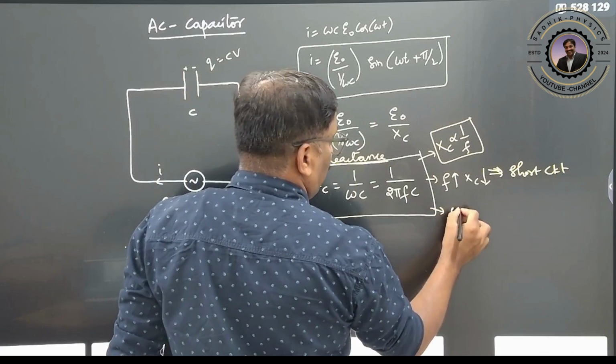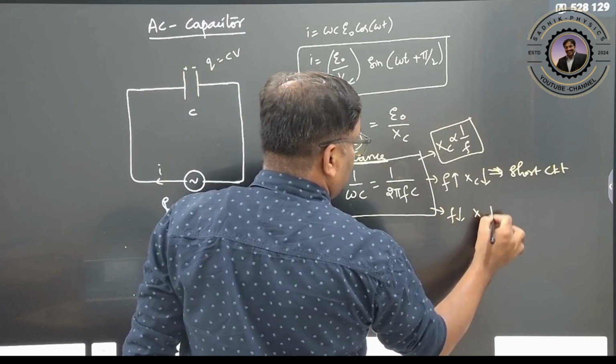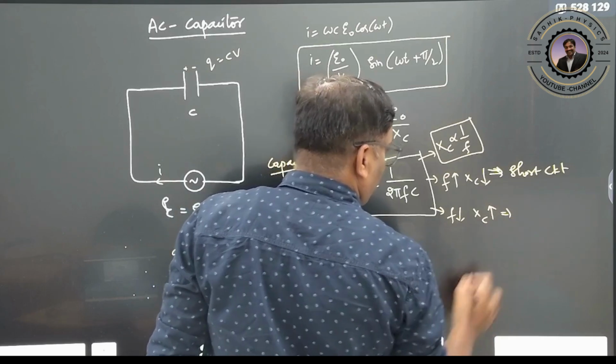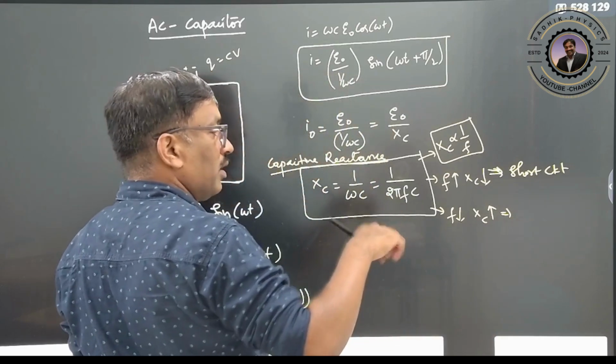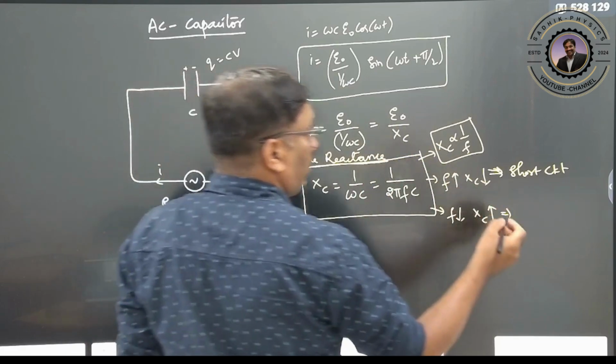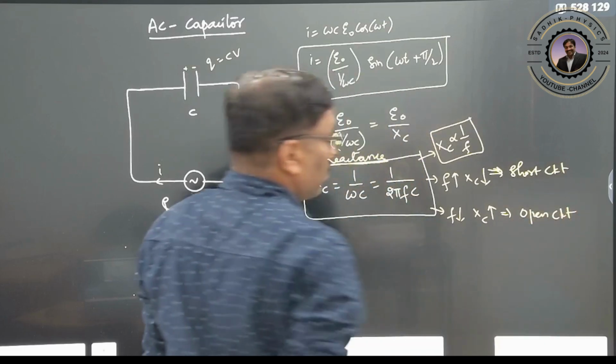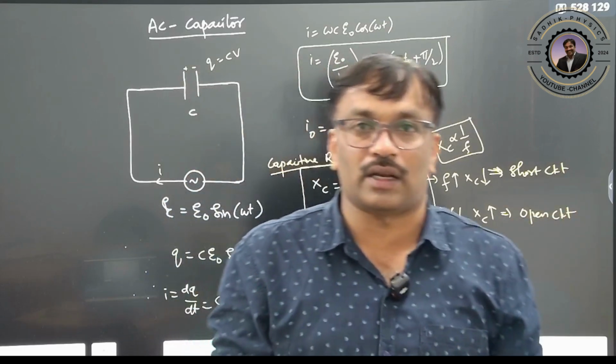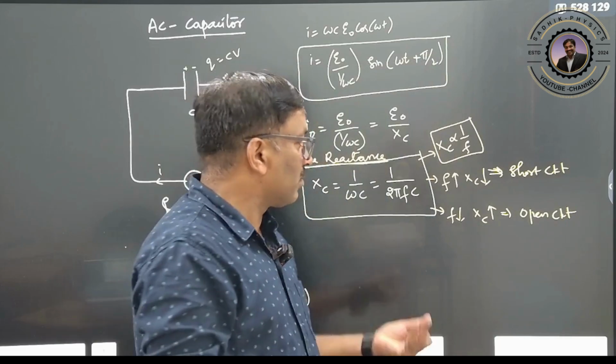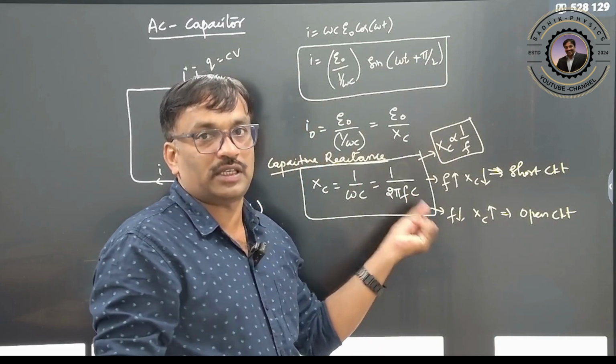At lower frequency, Xc will be larger. That means what will happen now? When the frequency is lower, Xc will be larger, therefore it will act like an open circuit. So that's why capacitor and inductor show some effect by changing the frequency.